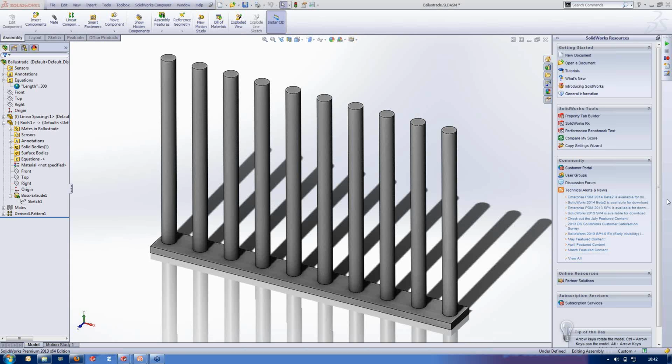We've got a question about covering any other statements in VBA. Historically, you could put any VBA statement that's solved in a single line into equations. They have changed the way SolidWorks reads syntax, and now it doesn't work that way. Unfortunately, if is still valid, but that is the only VBA statement that is valid where the syntax solves correctly. There are a couple of guys on the forum who have been trying some ways of getting VBA syntax into the equations, sort of shoehorning it in and ignoring errors. I have tried it myself and not had much luck. So at the moment, if you just stick to if as the only VBA statement that works in equations, you're going to be safe. Everything else, you're certainly going further than the functionality is intended to go, and I would expect it to fail, I'm afraid.